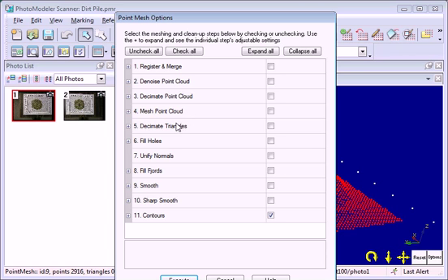If the resulting mesh is not smooth enough, we could select it and run just the smoothing steps. We would then have two triangulated meshes in the project, one without the smoothing steps and one with them. This allows you to compare the results. Or we could take that mesh and just run the decimate step to produce a second mesh with fewer triangles.